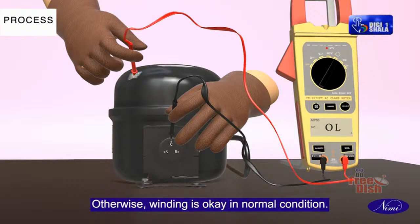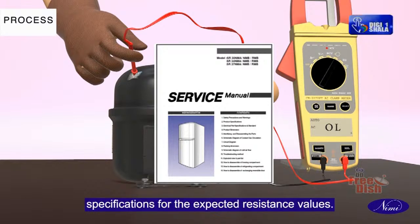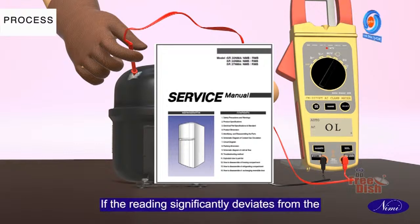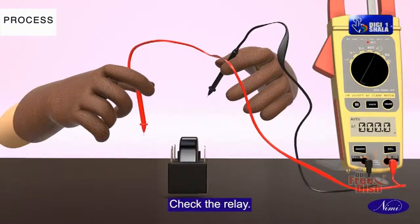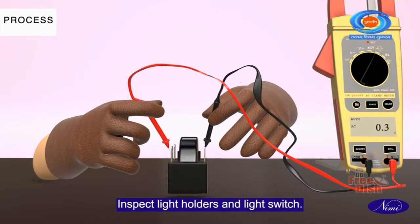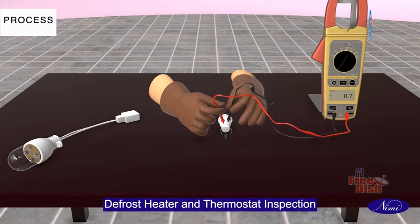Otherwise, winding is okay in normal condition. Refer to the refrigerator manual or technical specifications for the expected resistance values. If the reading significantly deviates from the expected values, the compressor might be faulty. Check the relay. Inspect light holders and light switch.